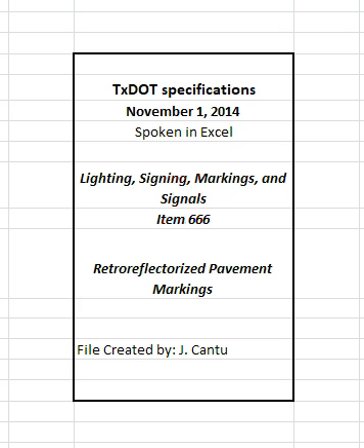Flush the spray head if spray application operations cease for 5 minutes or longer by spraying marking material into a pan or similar container until the material being applied is at the recommended temperature. Apply on clean, dry pavements passing the moisture test described in section 666.4.1, General, and with a surface temperature above 50 degrees Fahrenheit when measured in accordance with TxDOT 829B.